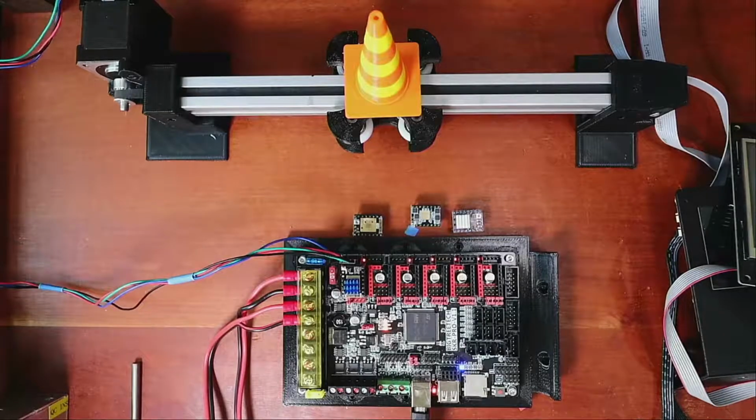Let me see what the chat's saying. It's not really an adventure, it's more like a journey. Just remember to take your time and do it step by step. So if your print's not working, change one thing, do a print, verify it, fix what needs to be fixed, then change another. If you do it all at once, it'll become very confusing very quickly.